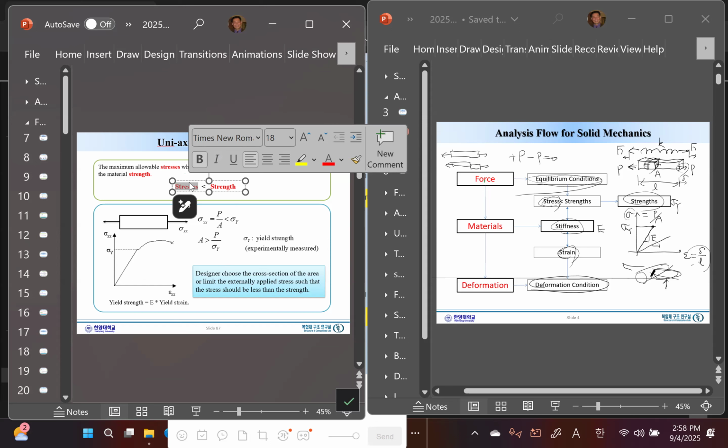That's why I'm saying that even though there's 1 point, the way you cut it, 3 components of stress will appear, forces will appear. So at 1 point we have 9 components. And how can the 9 components exist without causing any material failure? Just functioning as they should.